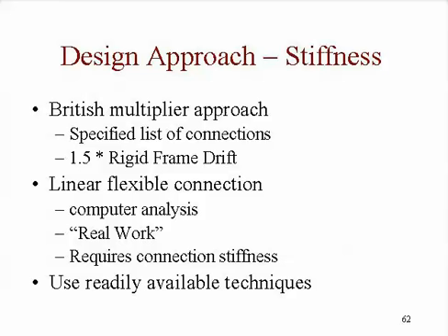And when they looked at the stiffness issues, they simply took a multiplier of 1.5. They said, just analyze the structure as a rigid frame and then multiply the deflection by 1.5. Now that works, but you have to recognize that they have a specific set of connections for which this system could be used. So as long as you're going to use their connections, their studies have said this will work.